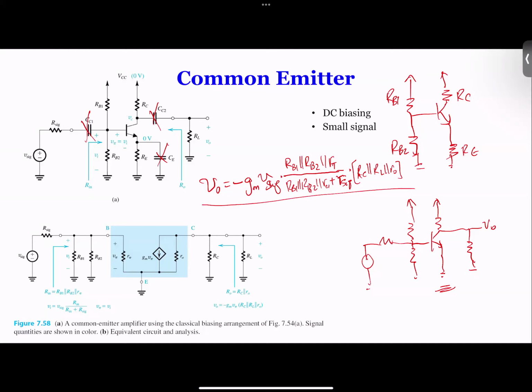Now, if we want to calculate the gain of the circuit, the gain usually is expressed as voltage gain, like AV. A means the amplification. So the voltage gain is called AV. The GM is sometimes called gain, but sometimes called transconductance. It's actually sometimes called the intrinsic gain.